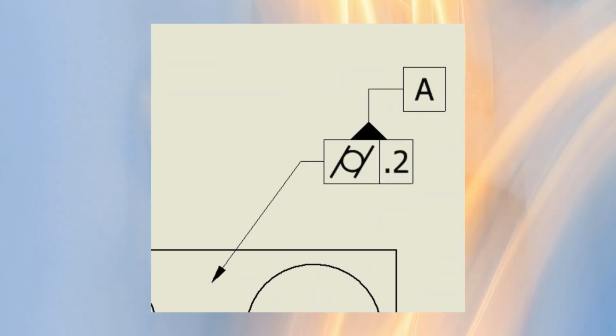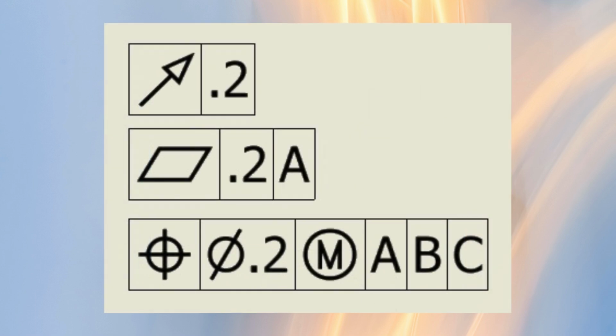When a datum is placed off a control frame, which we shall be looking at in a moment, and that frame is related to a surface, then the datum is geometrically controlled. A control frame, sometimes just referred to as a frame, exists to put a set of information together. This information will be regarding a feature of the part. Frames can be very simple as shown at the top of the picture. This frame simply has a symbol, in this case meaning runout, and a number which here is 0.2. This is telling us the runout allowed is a maximum of 0.2.